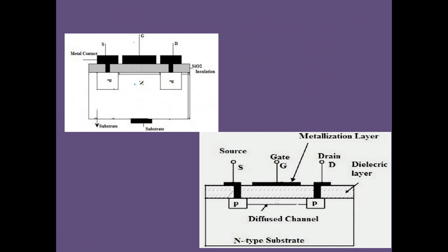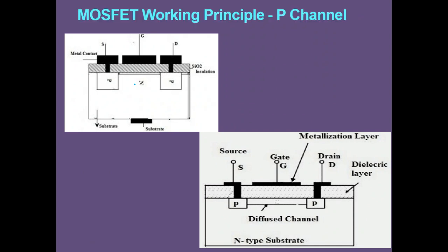Right? So far we have discussed the N channel D MOSFET. Coming to the P channel D MOSFET, instead of a lightly doped P type material, here we have taken N type material, and two heavily doped P regions are diffused over this metallic contact. Here this is SiO2. Through the metallic contact, the gate is made.